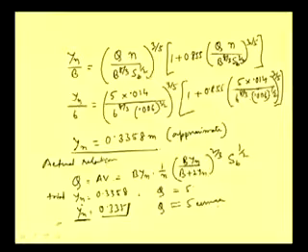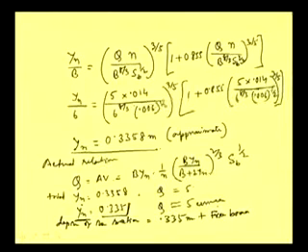That means the depth of the section is equal to 0.335 meter plus freeboard. As we have not discussed what the freeboard should be, right now I am keeping it as freeboard only, so that way we can design the channel well.